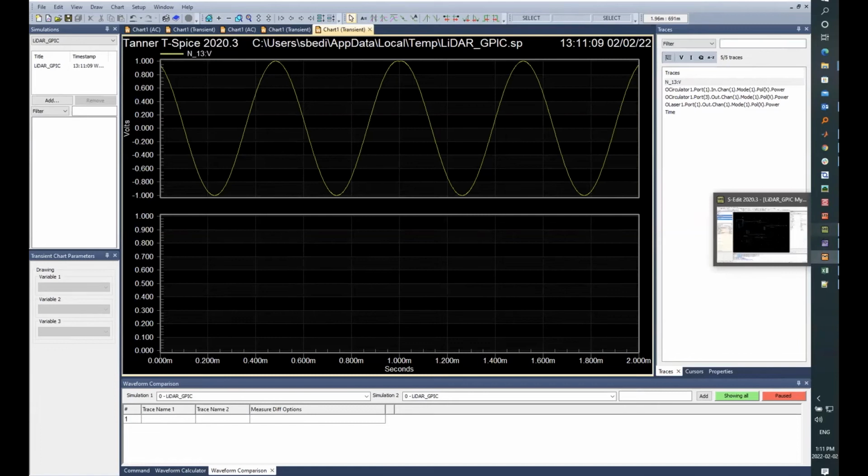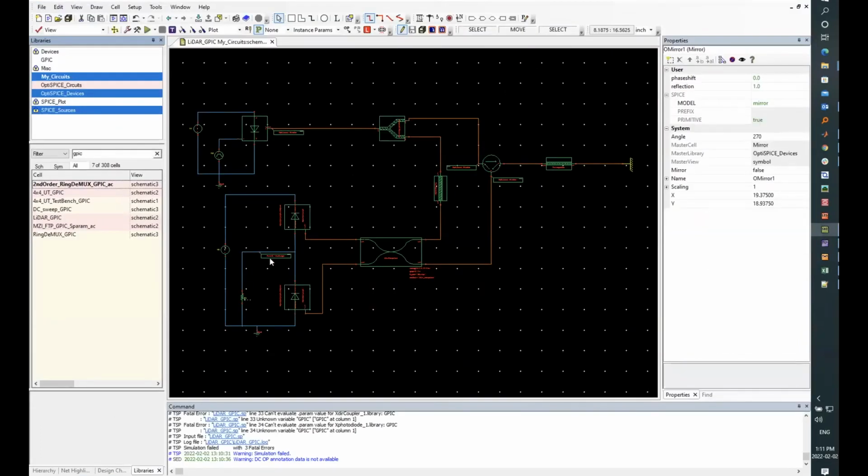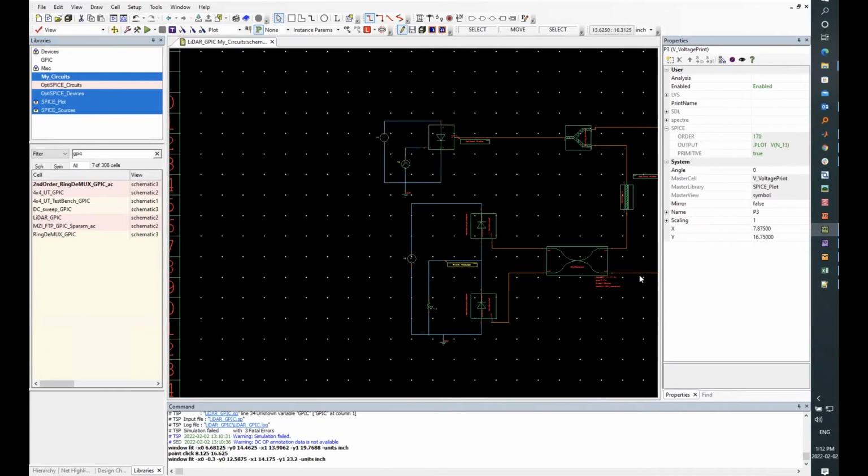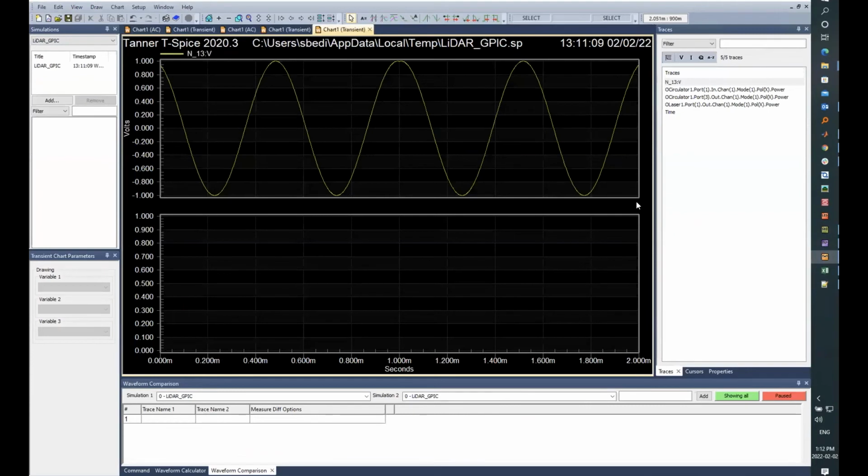All right, Chem. So we are measuring the difference here. Yeah, we're measuring the signal coming out of the two photodiodes. That's where we're getting the beat from. The signals are mixed right before the photodiode and then added together. The balanced detectors remove the DC offset. That's why you're seeing everything centered around 0. Right.